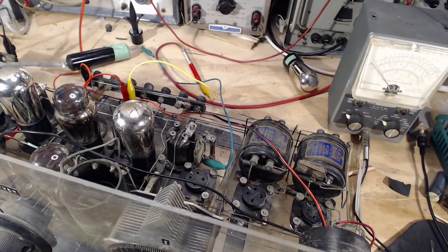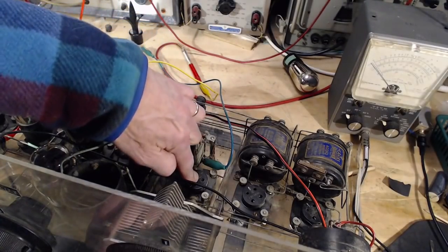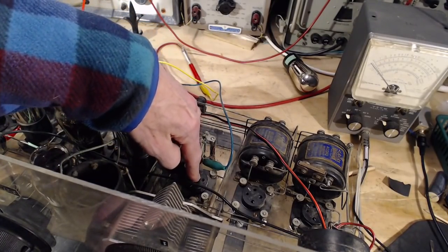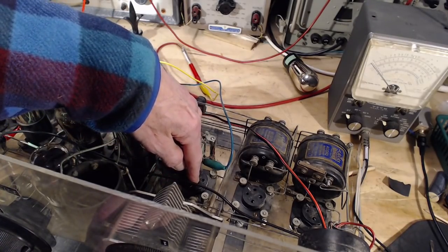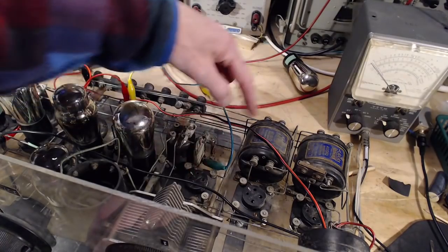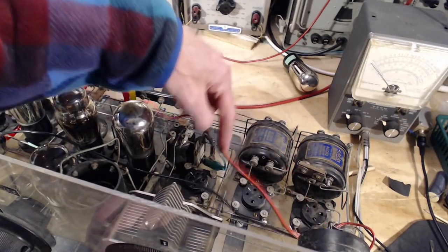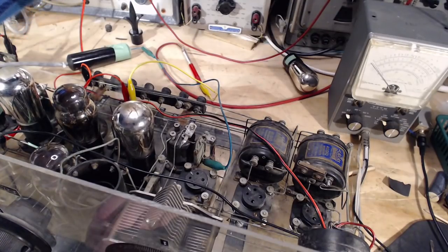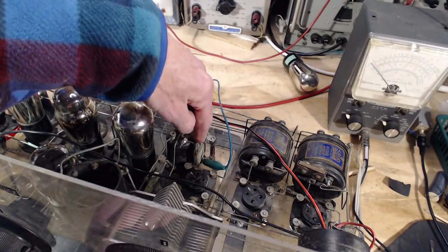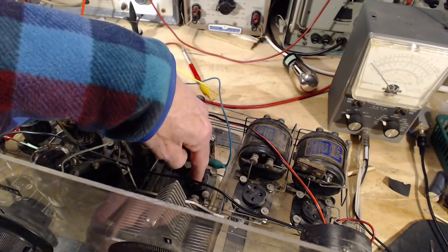Yeah, I did say something about setting this up would highlight problems for me, would make me spot problems. So here's one. I pulled the tube out of here because this tube is the first tube after the detector, and it's got a problem in that the plate voltage gets to it through the primary, and the primary is open. So there'd be no plate voltage, so no reason to have a tube here, so I pulled it out. But then I realized, wait a second, this is the grid leak detector, and it's looking for a tube. It needs the tube grid to do its job.